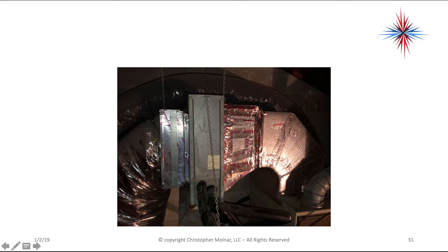Over here, though, you could see that the cut out of the coil is much smaller and squared off, okay? So we're coming out of a nice transition. We should be coming a similar transition back into appropriately sized ductwork, because air does not like sharp corners, okay? It doesn't like coming through here and hitting up against a wall. Okay, that will affect the entire airflow. Now notice the size here and the size here coming out of here, we're dropping in size.